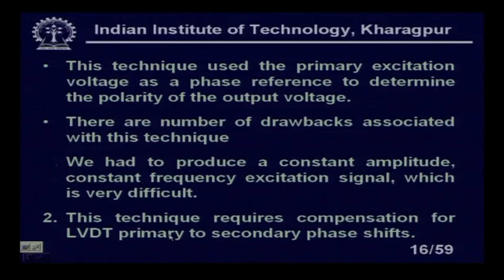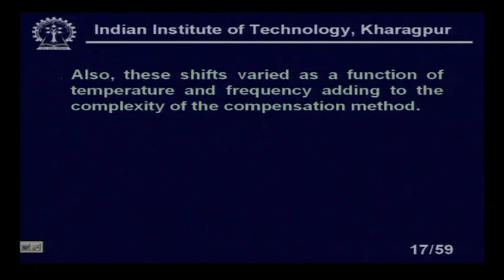This technique requires compensation for LVDT primary to secondary phase shifts. Also, these shifts varied as a function of temperature and frequency, adding to the complexity of the compensation method. Okay. So, this whole thing can be avoided.